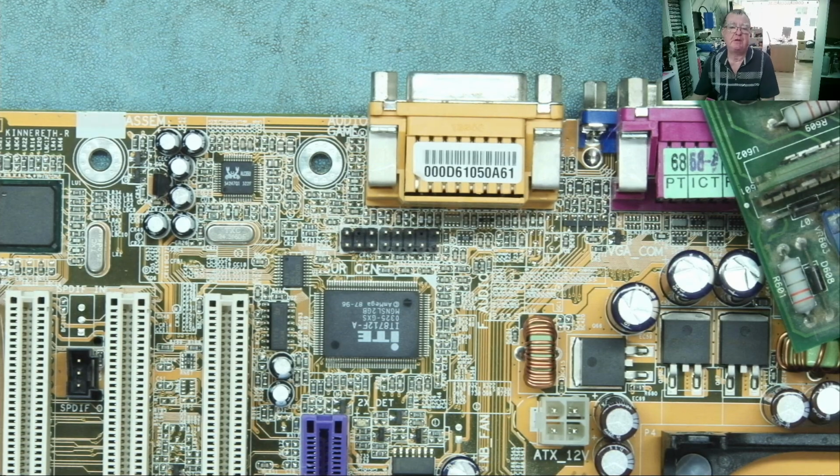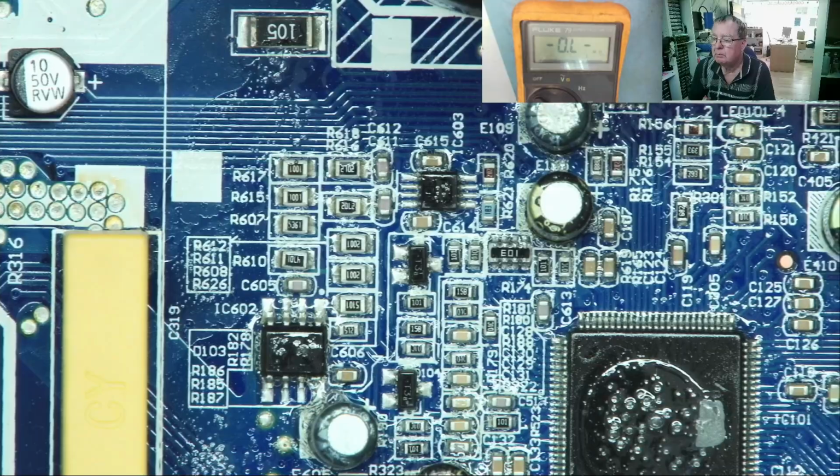The 2 most important things about resistors then. When resistors fail, they fail by going high resistance. The resistance increases, sometimes to infinity basically because they become open circuit, but the resistance will increase when they fail. And I would say always. When you measure with a multimeter in circuit, you may find when you measure them, they read lower than the rated value.